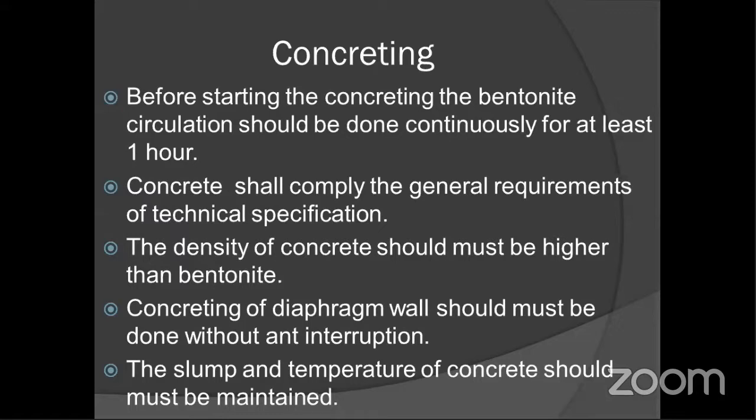The concreting will be done through tremie pipes of 250 to 300 mm diameter, which should be joined properly and lowered inside the trench.